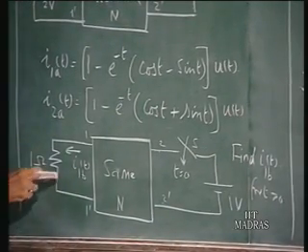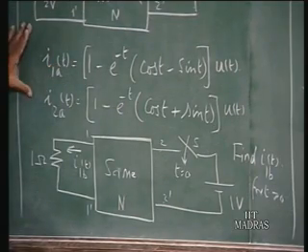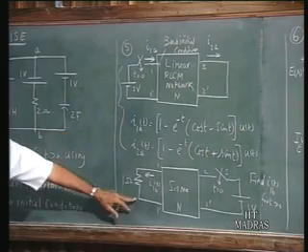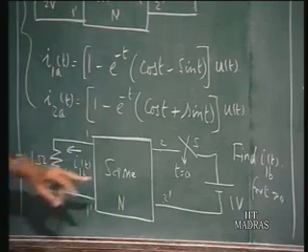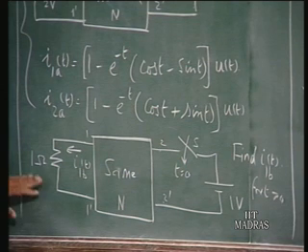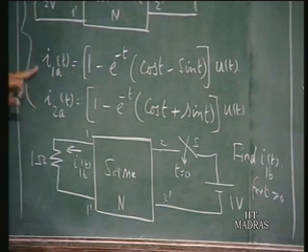So you find I1B here using the data that is available in the first set of excitations. This is all one set of excitations. Using this in the second set of conditions, find I1B for t greater than 0, again using possibly the reciprocity theorem, possibly the substitution theorem, whatever, and the superposition principle. So find I1B of t in the second set of excitation conditions using the data in the first set.